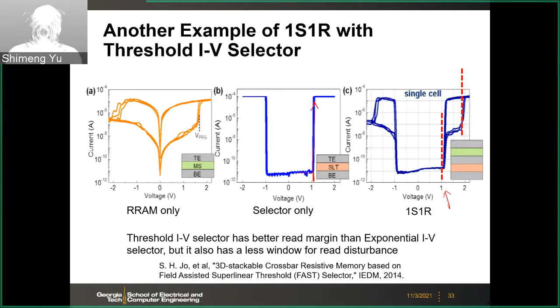The reason is that this is your V, and if this is a half V, you see that the on-off ratio, or nonlinearity ratio, between those two points, you completely cut off the current. So the ratio in this case will be huge. This is in log scale.